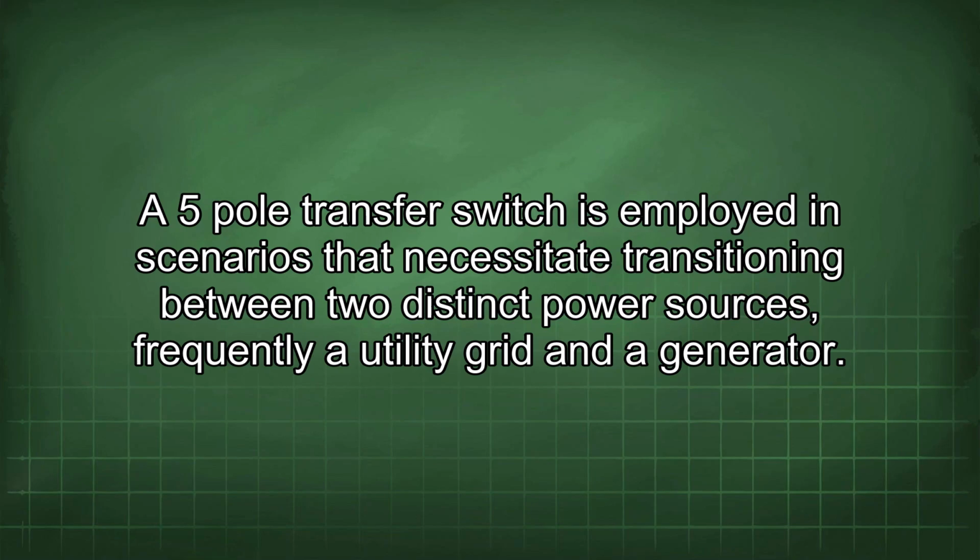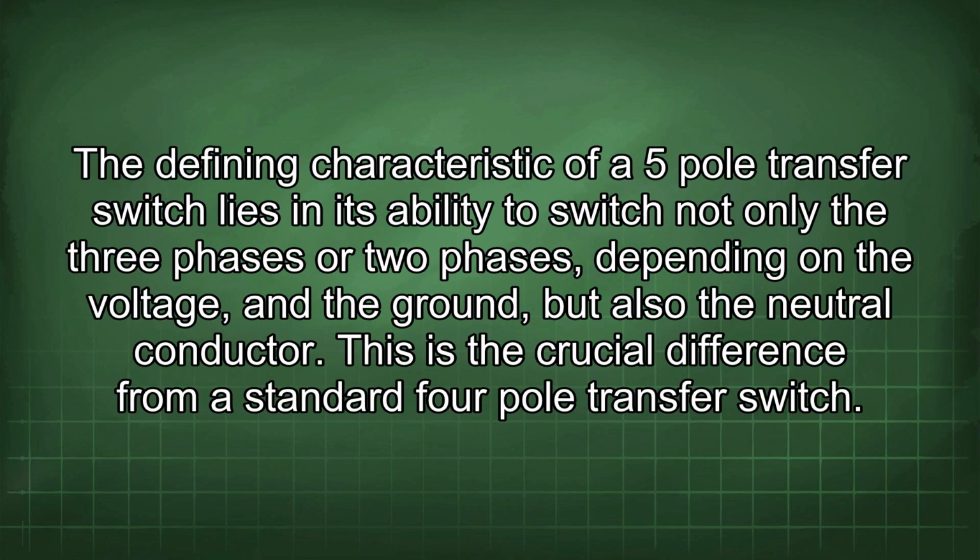5-pole transfer switches are employed in scenarios that necessitate transitioning between two distinct power sources, frequently a utility grid and a generator. The defining characteristic of a 5-pole transfer switch lies in its ability to switch not only the 3 phases, or 2 phases depending on the voltage, and the ground, but also the neutral conductor. This is the crucial difference from a standard 4-pole transfer switch.